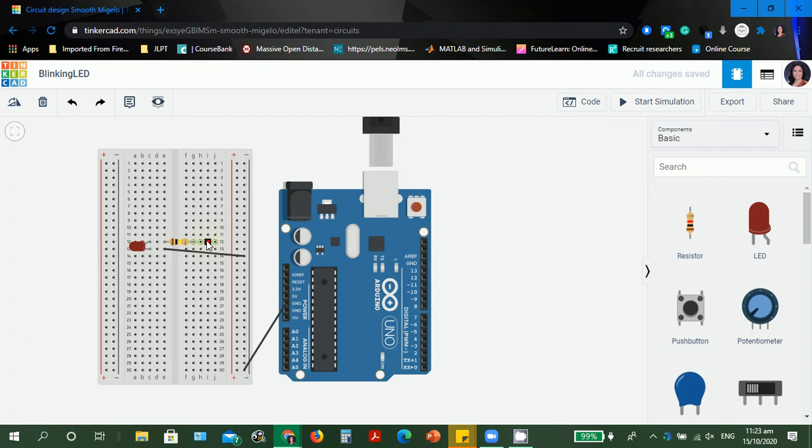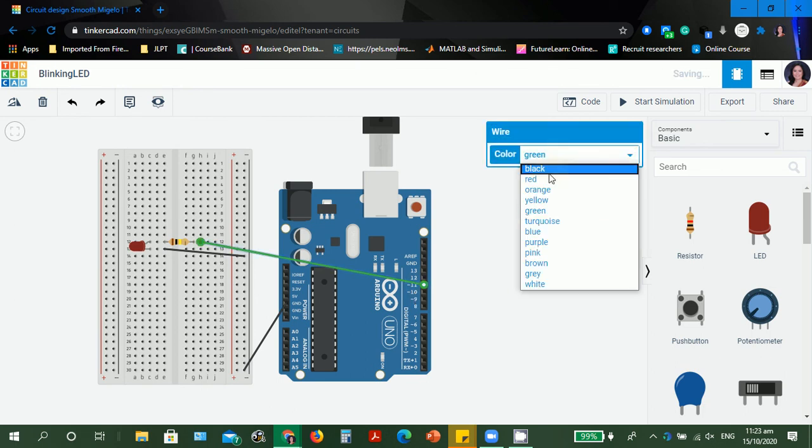So since we've assigned our pin to pin 11, any points from here are the signal for the anode of the LED. So we have 1, 2, 3 more points. And anywhere from these 3 points, for example, I want the wire to start from here and then go to pin number 11. And then let's make it red, for example.